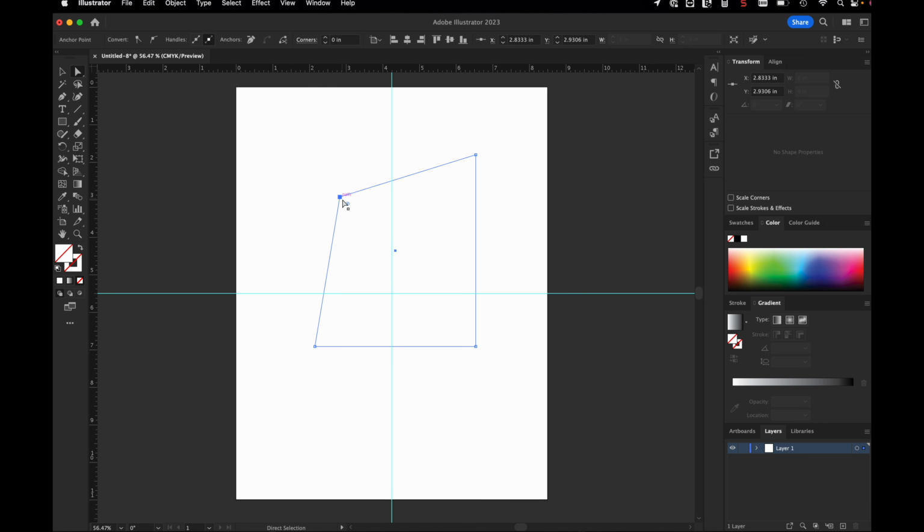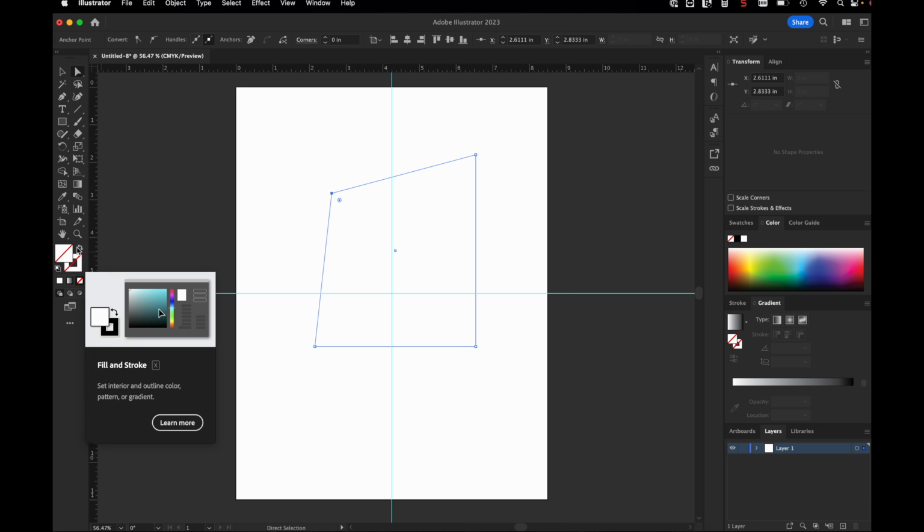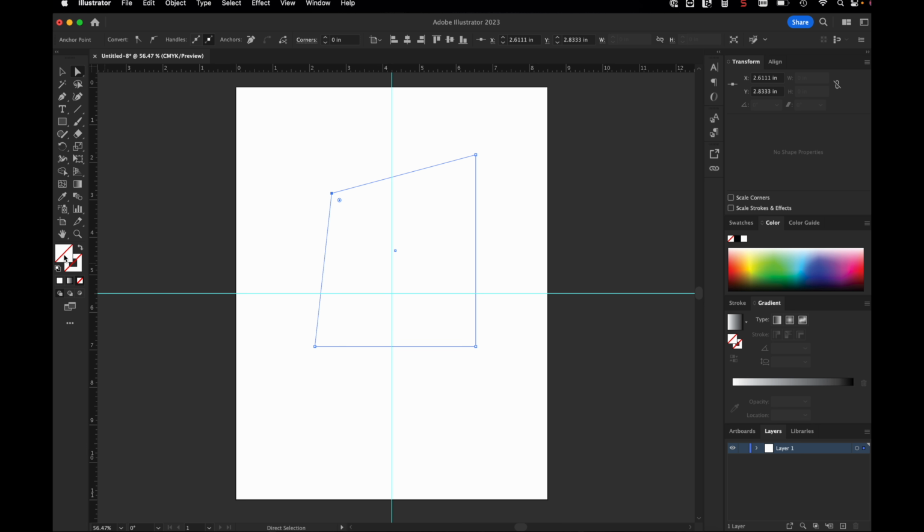But notice that when I do that, there is no fill or anything, so it's not predefined, because of the colors right now. When you see this color box for the fill and the line color, when you see the red line, that means that there is no color defined. So to change that, let's change the fill. Select the fill, make sure that's selected, and then the color window over here, when you move into it, notice it changes to an eyedropper. If you just click, it changes the color fill. Now if you want to change the line color, click the line and you do the same thing.